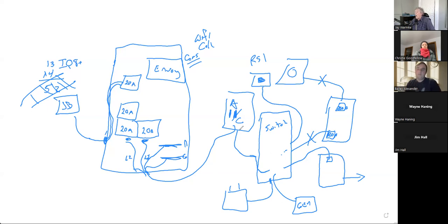Well, what happens if your house is on fire and the grid went down because they came and they turned off the system? Well, the first thing they did is they pulled the meter. That shut off the grid. Then they turned off the array. So that turned off the power here, but now your batteries kick in or your generator kicks in because you still want power. The switch is still figuring out, yeah, okay, well, we're still going to power the loads. So there's still live lines in your house. Even though the first responders have pulled the meter and they pulled the AC disconnect.